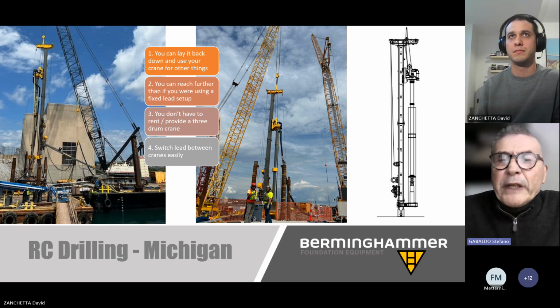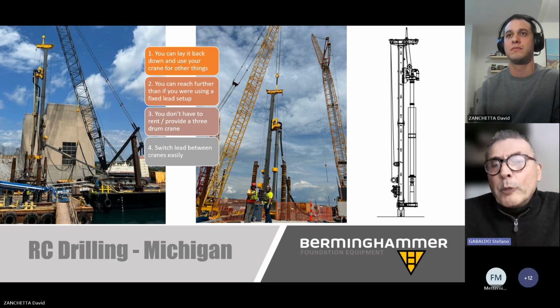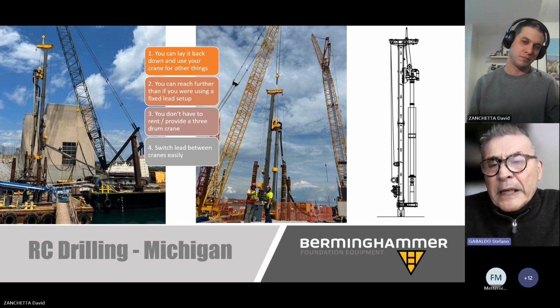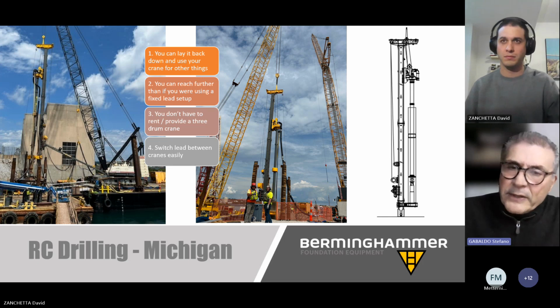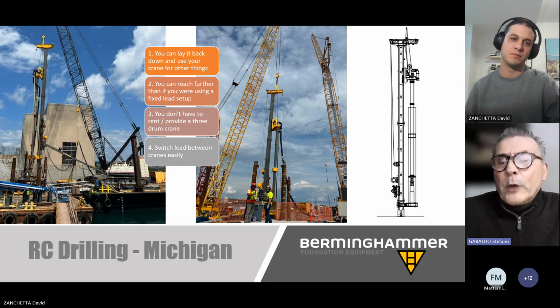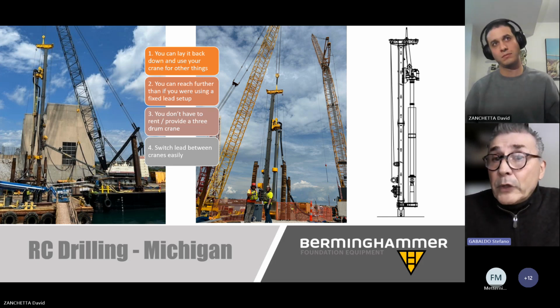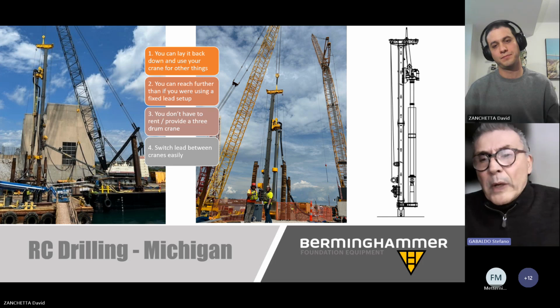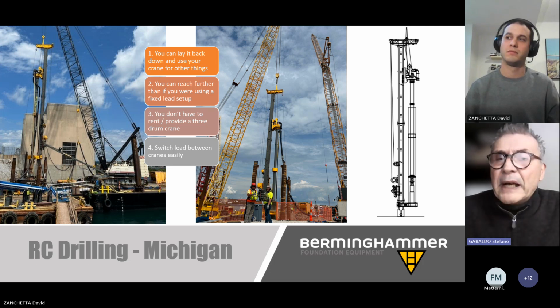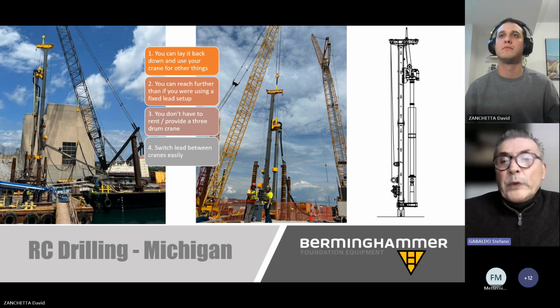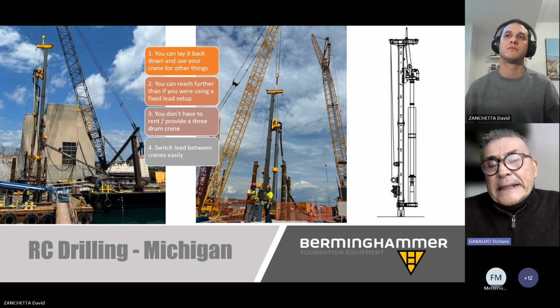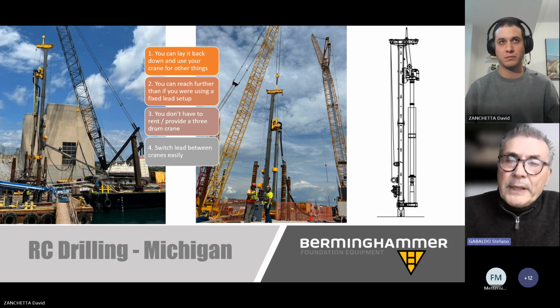Another way we can do it, if it is a rock socket, for instance, on a long pile, with our clamp on the pile, we can exert an upward pressure for the capacity of the pile itself. If this pile were pre-driven by an impact hammer, and then we go in and clean it, and then do the rock socket below that doesn't require a downhole hammer, and you want to do it with a standard RC rotary drill, we can apply, without having extra weight, the same force as the ability of the pile itself to resist tension.